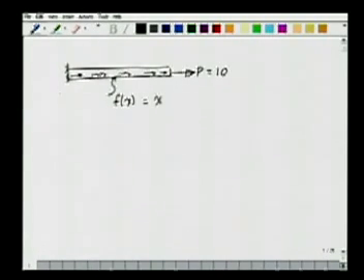At x equal to 0, we had fixed the bar, that is, this was a fixed boundary condition, and at x equal to 1, we had the P applied, that is, the force was applied at x equal to 1. For this problem, we wanted to get an approximate solution using the Rayleigh method. So how did we proceed?